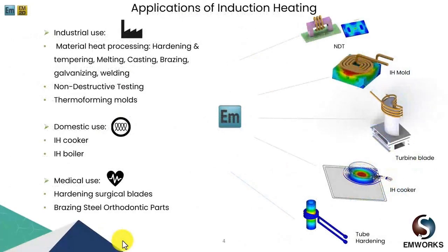Now, let's have a look at some of the main induction heating applications for the industrial domain. Induction heating is essential for heat processing, where highly repetitive heating operations are performed, especially for material heat processing like hardening and tempering, melting, casting, brazing, and even preheating for welding.